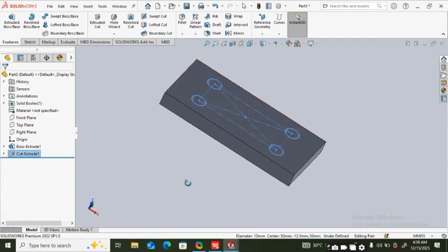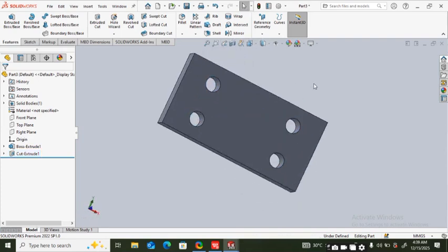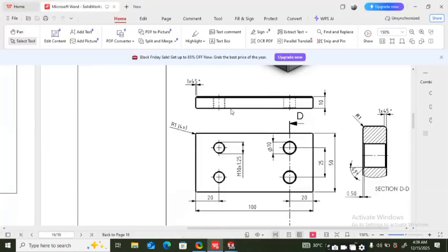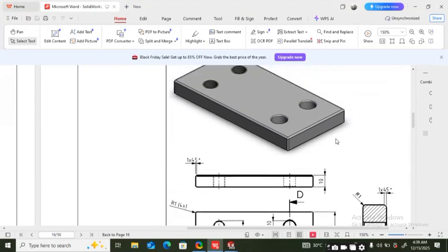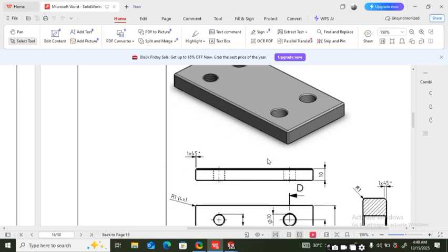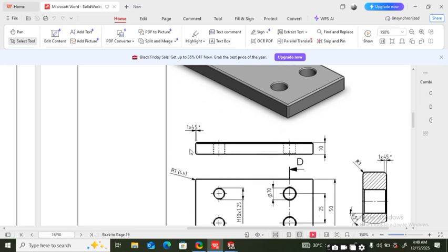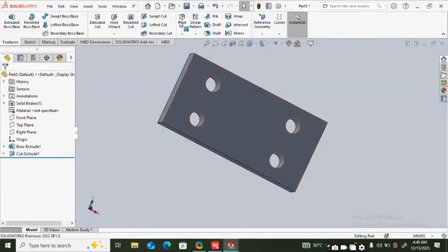So now our circle is formed. The first circle has been formed. So the next thing now is to give it a fillet. Fillets in the sense that each of these parts were given some kind of smoothness, some fillet, which makes it the model we see today. And each fillet is given to us as 1 at 45 degrees, and also the fillet around the side is also 1. So now back to SolidWorks, go to your fillets.